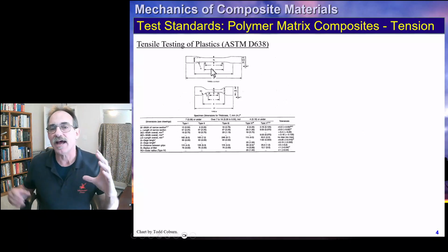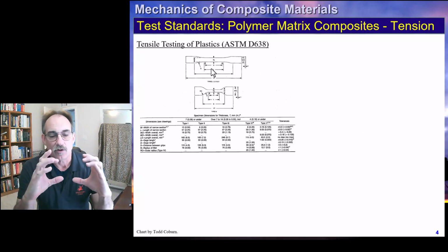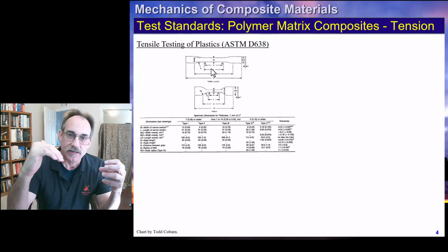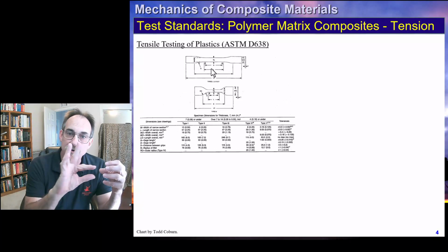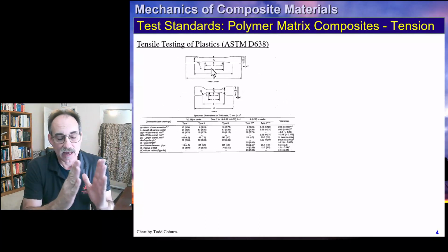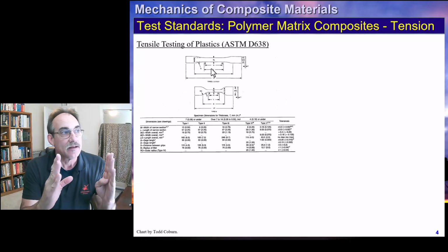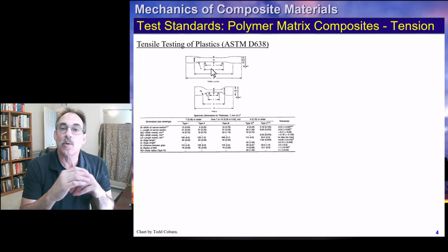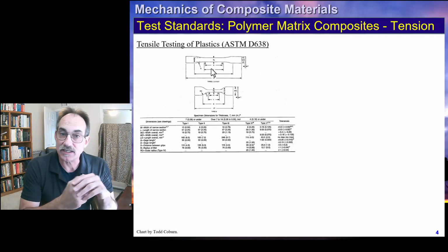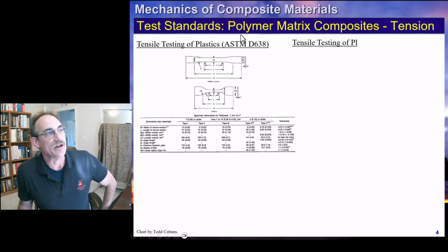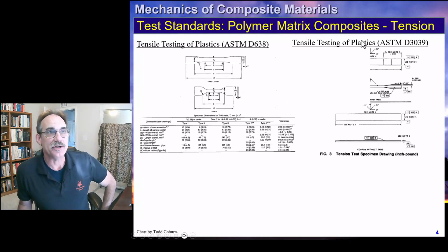You'll notice they're long enough so you can grab them with the grips. They have a nice, even distribution of material so that your stress riser is not too much, and they've got a long enough grip length, a long enough point where you can evaluate the loading with no tweaks from where the grips are applied in order to get good data and maybe fit an extensometer in there. So for tension testing, these are pretty good. It lists out a bunch of different methods you can use.